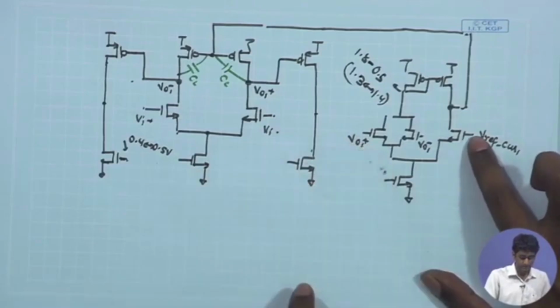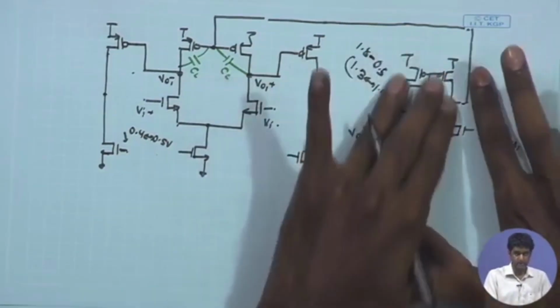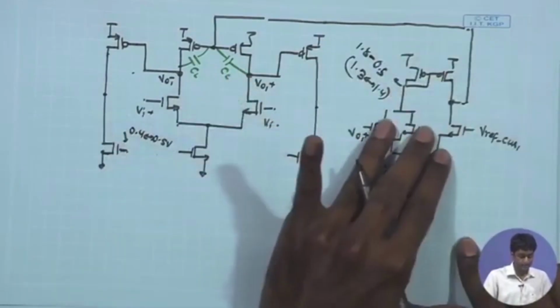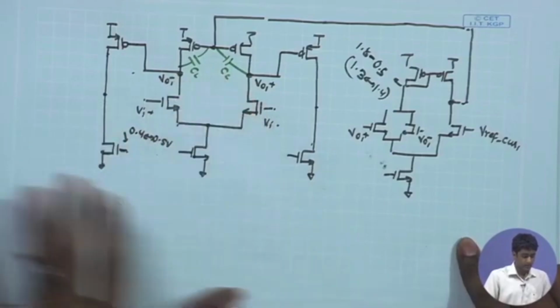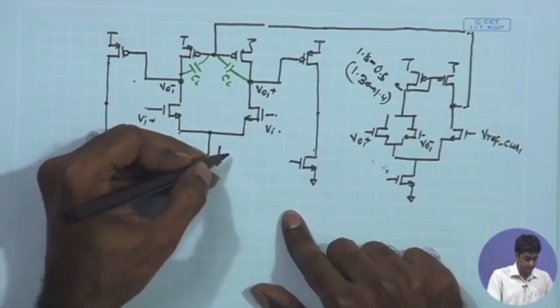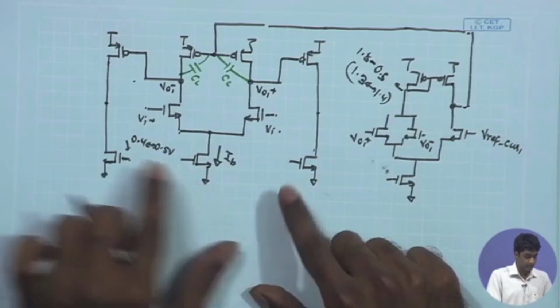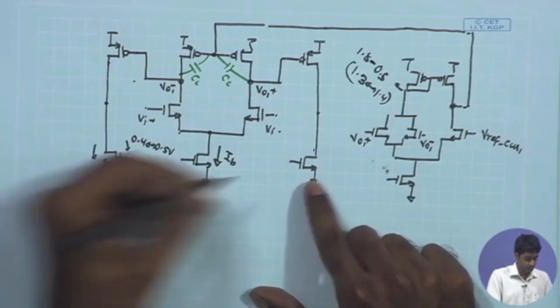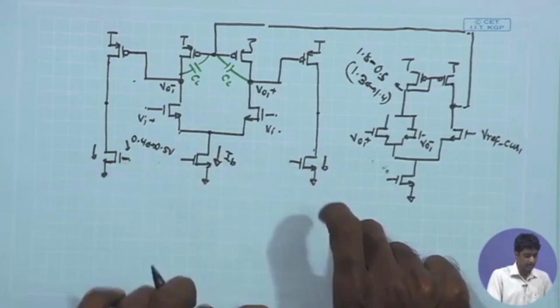and accordingly we also need to see what is the VCM ref that we are putting for the first stage, in order to see whether this amplifier is going to work properly if I am using it only for the first stage. Now, if I look at the DC conditions for the current biasing, I am using some I bias with the help of this current mirror, and I also may be using the same I bias in these two branches.